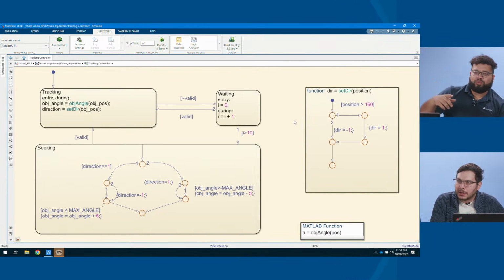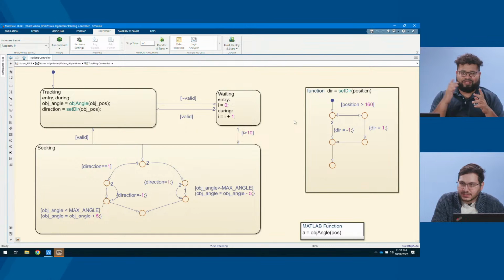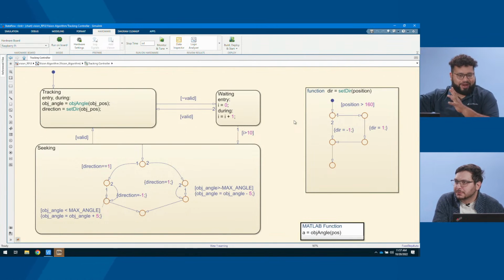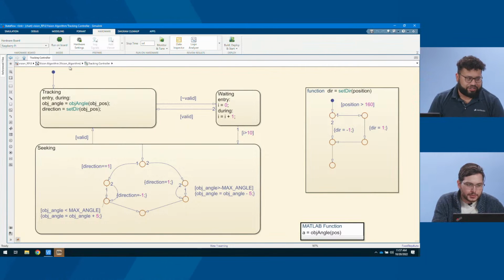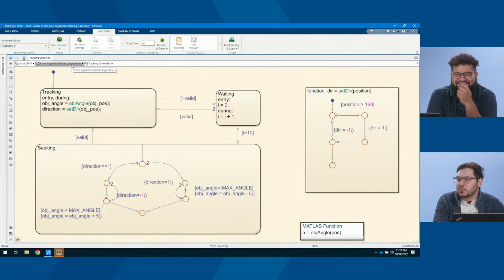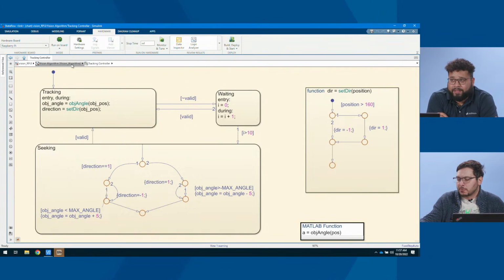What that's doing is saying, if it's from 0 to 160, it's on the left-hand side, so it'll turn to the left. And if it's 160 to 320, it's on the right-hand side. So it's setting that -1 or +1 direction. So yes, it does, but very crudely. It's got a dead zone set up, so if it's near the center, it won't try to change the angle. But when you move it side to side, it just says, well, the green circle is moving to the left side of the image, so I want the servo to turn to the left some.